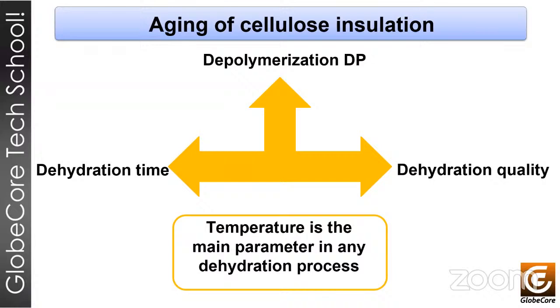For the moisture removal to be effective, many limitations must be taken into account when heating. Sometimes there may be uneven temperature spread inside the transformer. In such a case, some parts of the transformer may be too cold and others too hot. Therefore, equable heating in combination with vacuuming is the main factor to improve the quality of the dehydration, reducing the time required for it and slowing down the depolymerization of paper insulation, which improves the mechanical properties of the insulation.